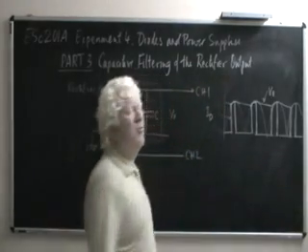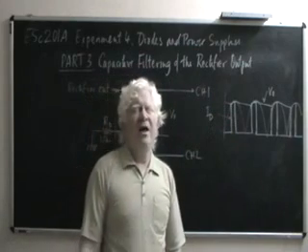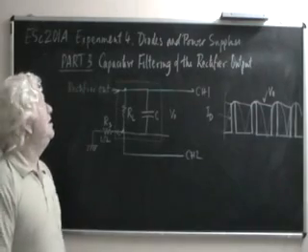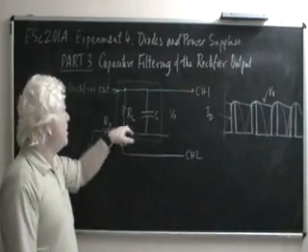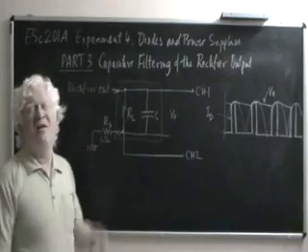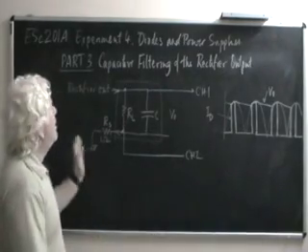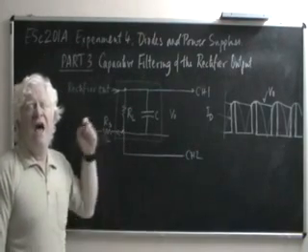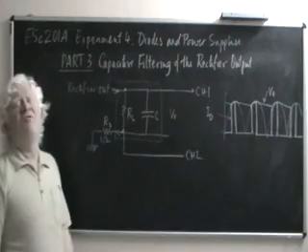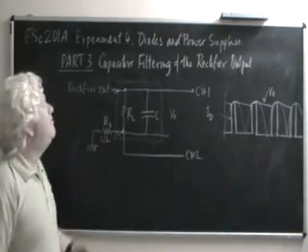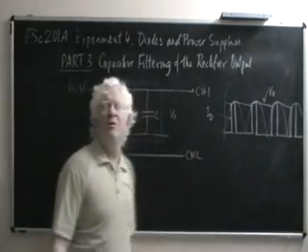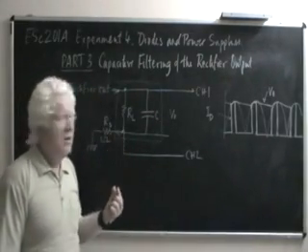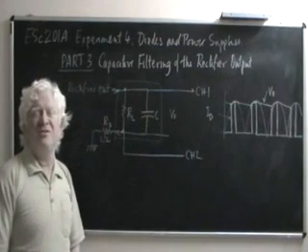The diode current waveform would look like this. The diode indeed has to pass a reasonably large amount of current to maintain even a moderate amount of current in the load resistor for the entire cycle. Because all the current that flows through the load resistor over the entire cycle has to be supplied in terms of an equivalent amount of charge over a very, very small fraction of that interval. And that fraction gets smaller and smaller as the capacitance gets larger and larger.